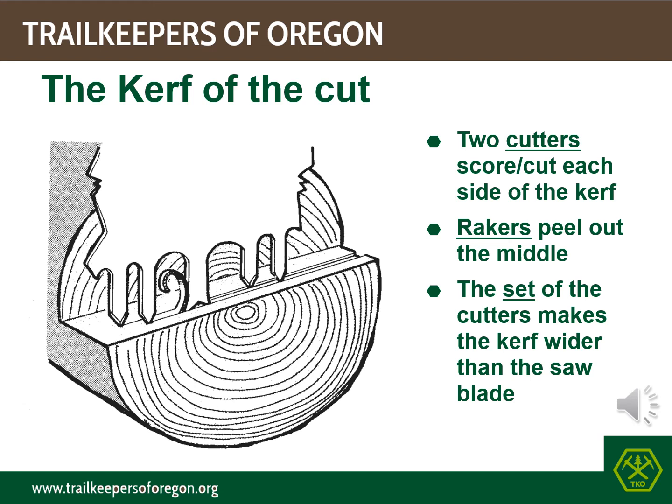When rakers are shaped properly and their depth has been set accurately, they pull out long shavings of wood, called noodles, rather than sawdust. Wet or green wood is hard to remove from the kerf because it is so resilient. The cut fiber bounces back.